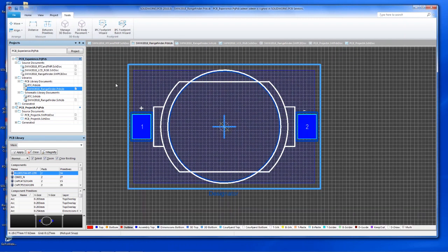Simply by clicking the number 2 and number 3, we are switching between our two-dimensional view and our three-dimensional view. The models that are embedded onto your SolidWorks PCB footprints are the models that will directly collaborate to SolidWorks. You have the capability to add SolidWorks part models, step files, parasolid files, or you can use the internal 3D model creation tools to develop your own models within the PCB tool.